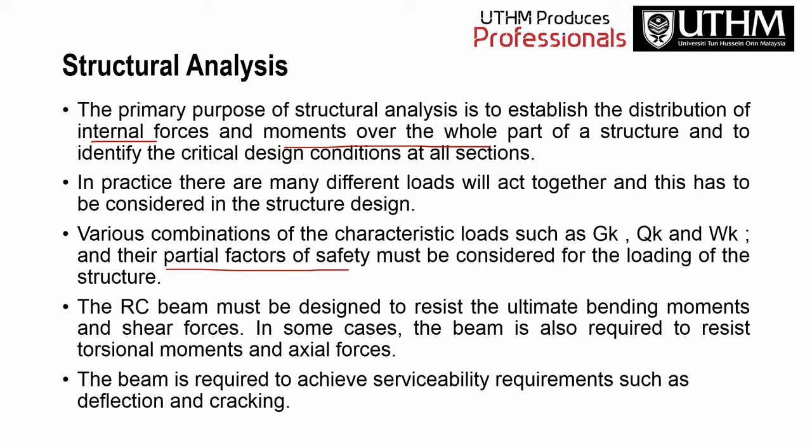okay. So the RC beam must be designed to resist the ultimate bending moments and shear force. In some cases, the beam is also required to resist torsional moments and also axial force. So the beam is required to achieve serviceability requirements such as deflections and cracking.